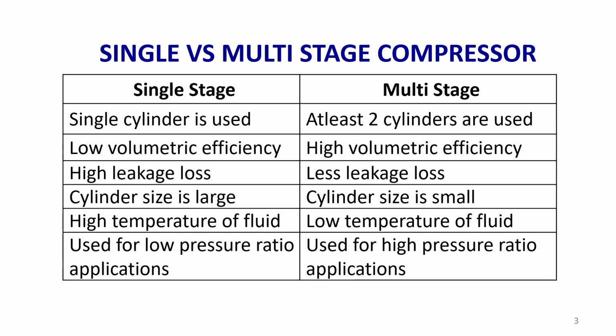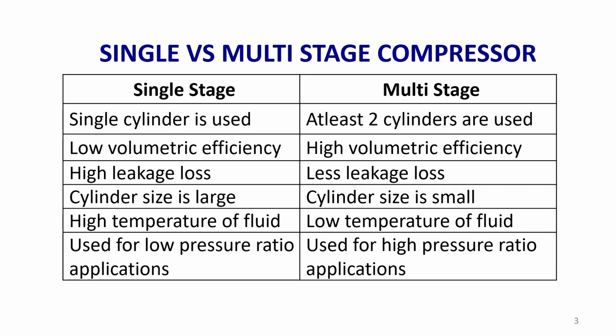If we look at the comparison between single stage and multi-stage, as the name indicates, in single stage there is only one stage, one piston cylinder arrangement. In case of multi-stage, more than one piston cylinder arrangement is used. So the first point is that a single cylinder is used, and in multi-stage at least two cylinders would be used, a low pressure cylinder and a high pressure cylinder. If the number of stages is 3, then 3 cylinders would be used.